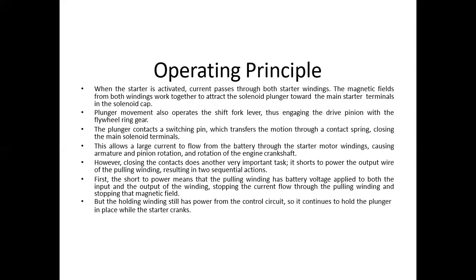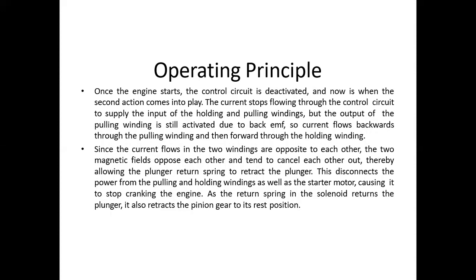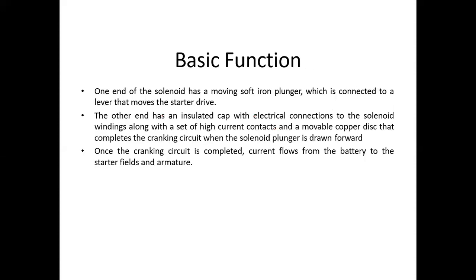However, closing the contacts does another very important task. It shorts power to the output wire of the pulling winding, resulting in two sequential actions. First, the holding winding still has power from the control circuit, so it continues to hold the plunger in place while the starter cranks. These are the basic operations.